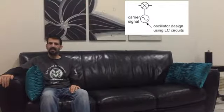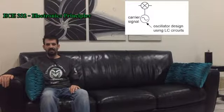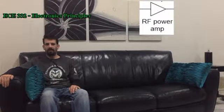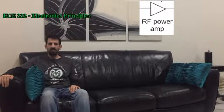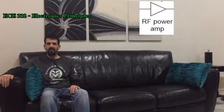Shifting back to ECE 332, the output of the mixer is sent to the RF power amplifier. So far, the power of the signal has been on the order of microwatts, and the antenna needs to run on the order of milliwatts, which is 3 orders of magnitude greater than what the mixer can supply.